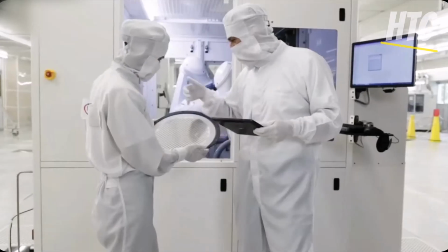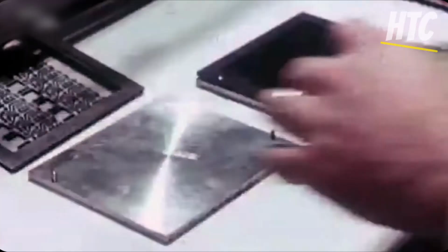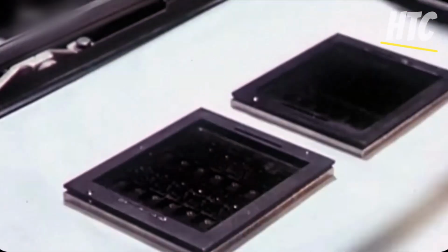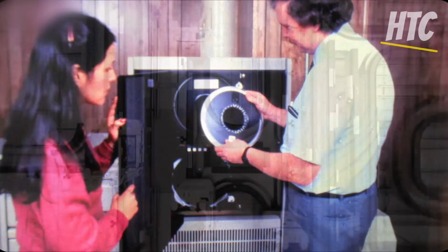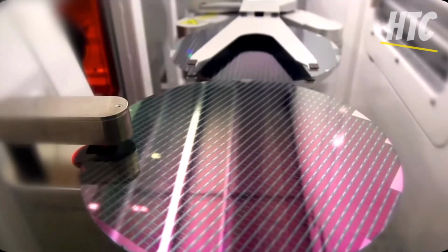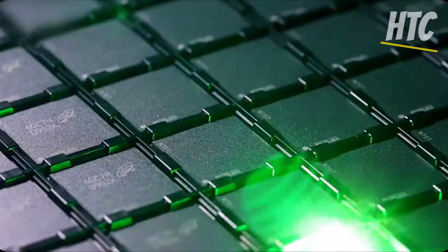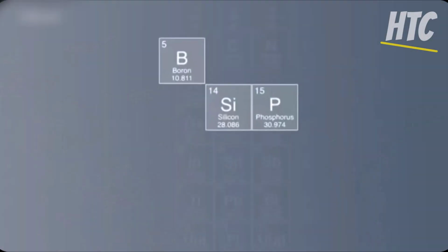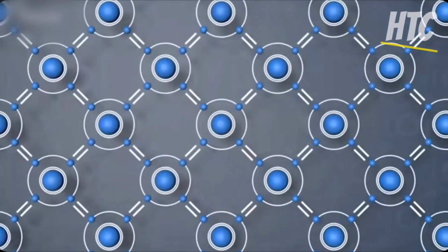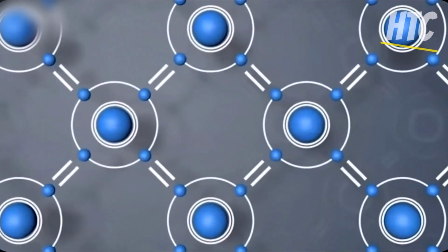Advanced techniques, including extreme ultraviolet (EUV) lithography, are used for nodes below 10 nanometers, allowing manufacturers to achieve finer resolutions with precision previously thought impossible. Once exposed, the wafer undergoes development to remove either the exposed or unexposed photoresist, leaving behind the exact pattern of the CPU circuitry.